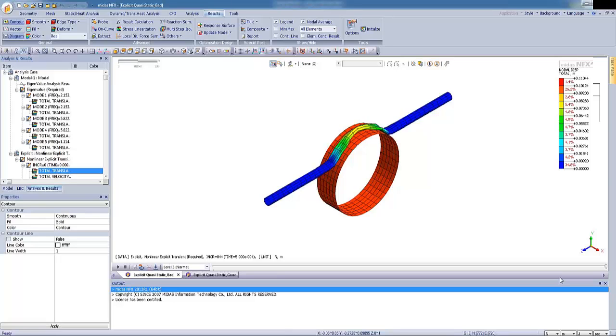So how do we actually set up the model to achieve structural response? You have to remember a few things. First of all, we have to assign the proper velocity value to the system. We have to perform modal analysis to extract the first natural frequency, and this will be the dominant response for your quasi-static event. The next step is calculating the corresponding time period using the first natural frequency of the model.